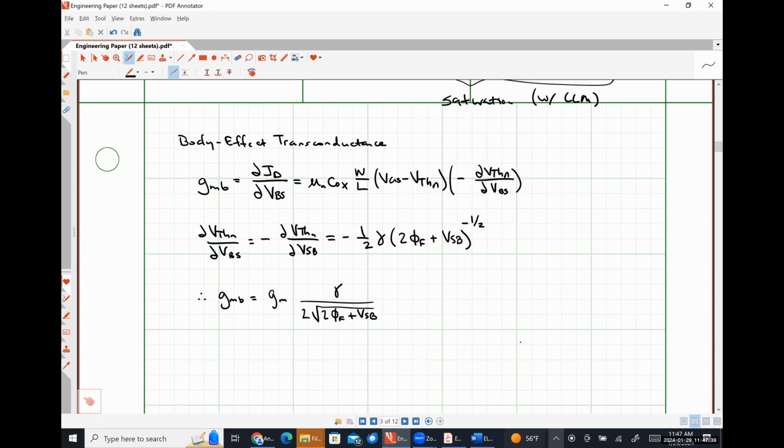So this is a little something that might seem a bit odd, but we know in a DC MOSFET circuit, our gate current is 0. And we've been saying it's 0 because effectively the gate forms a capacitor with the substrate and all of that kind of stuff. So for DC, no current whatsoever. For small signal, we're also going to say that it forms a capacitor, but we know that capacitors have impedance, right? So we need to be careful about what frequencies we're talking about, okay?